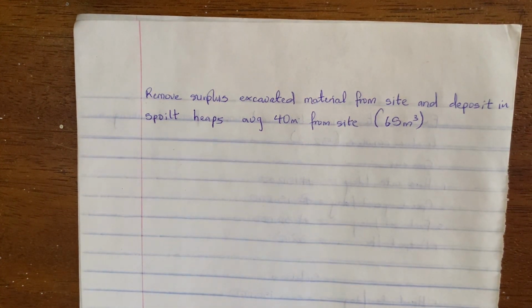So we're going to be making assumptions that the labor constant, or the time it will take the laborer to carry out all this operation, is 1.75 hours. And the capacity of this wheelbarrow is 0.2 meter cube. So it means that the capacity or the volume of excavated soil which can enter into the wheelbarrow is 0.2 meter cube. So with those two parameters, we can now start building up our rate.